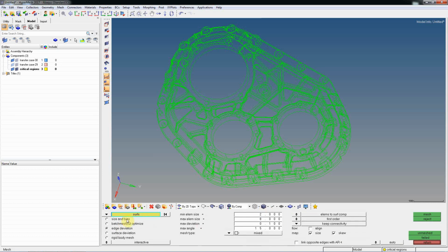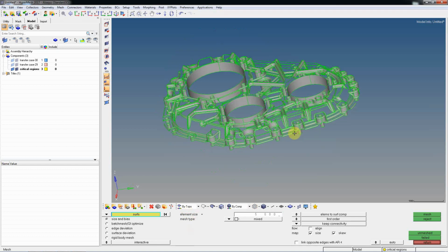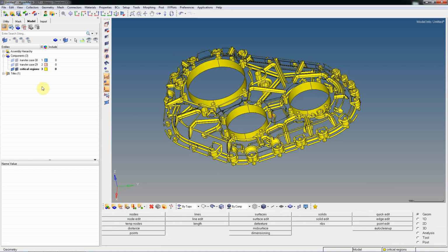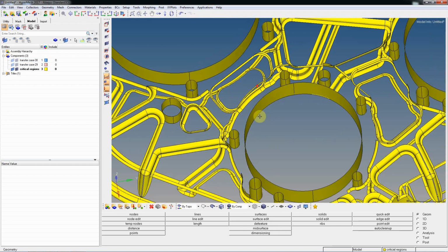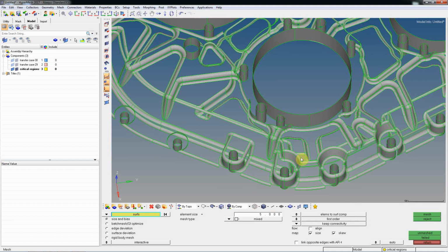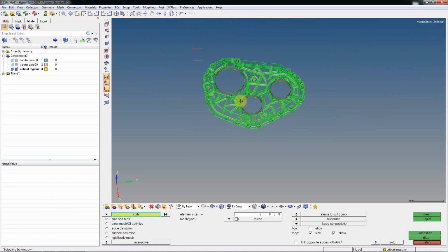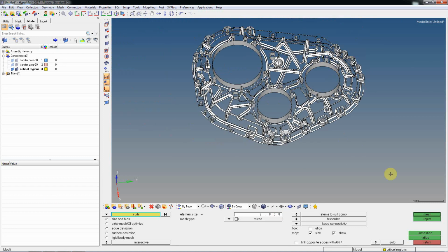In this, what I need to do, you can switch off this planar area, right? You can switch off this planar area and work with this critical area. As I said, these are the critical regions. So I'll take the minimum element, select those things and mesh.